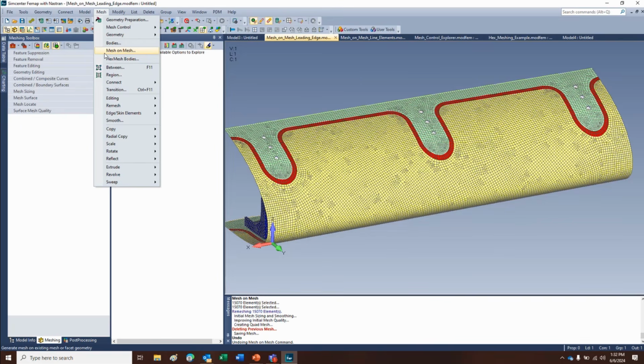And then you can even use it to mesh, let's say you have a real pain in the neck piece of solid geometry and you want to TEP mesh it. Instead of using our geometry preparation command, you can now just use the body mesher instead, and it just goes over any internal curves or anything like that. So when you're using mesh bodies, that now does follow our mesh hard points. So if you put them into the mesh, it should take care of them. I just don't think we did it for mesh on mesh yet.